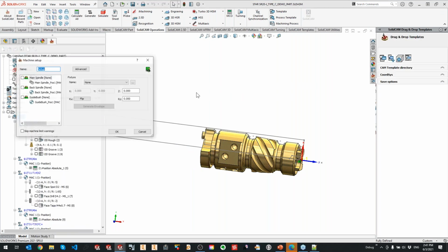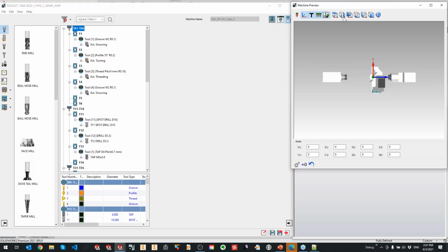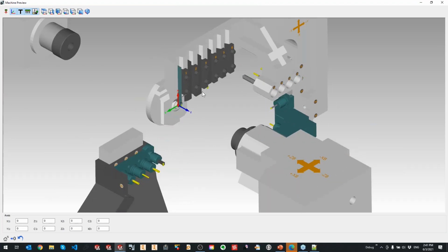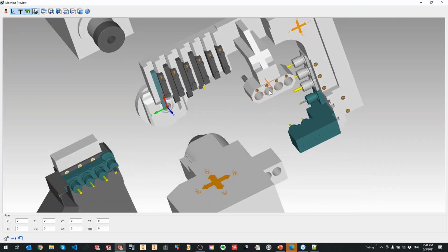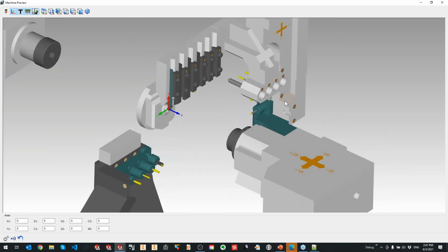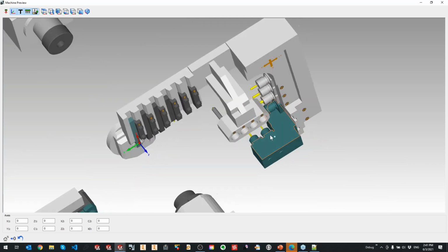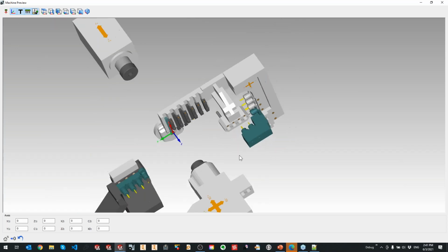And let me just quickly show you what this machine looks like so you have a better overview. It has one gang tool which allows you 6 turning tools over here. Some tools, front drilling, or also turning tools on the front, and many radial tools on the side in channel 1. Also, there is a possibility to attach the holder, which will allow you to have front face milling operations.